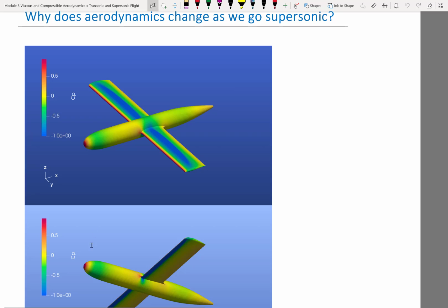All right, and just watch carefully the pressure on top of the wing. Okay, so still, this is a highly cambered airfoil, right? And from thin airfoil theory, we know that even in incompressible situations, very low Mach number, we would have the highest suction, the lowest pressure, somewhere not exactly on the leading edge, but somewhere between the quarter chord and the half chord, right?